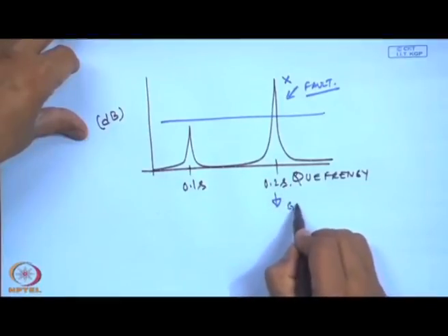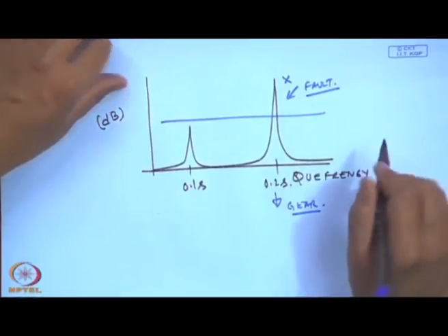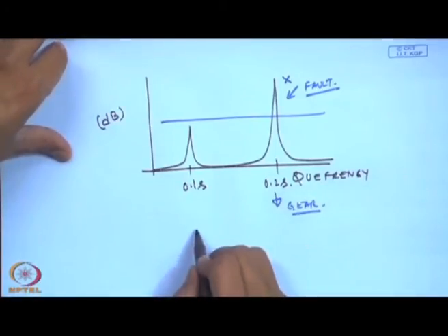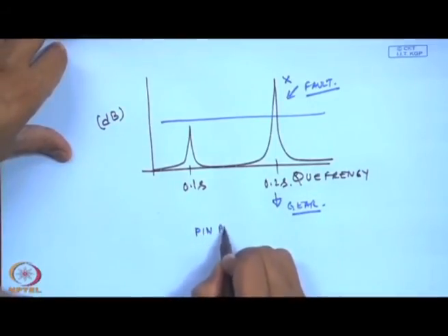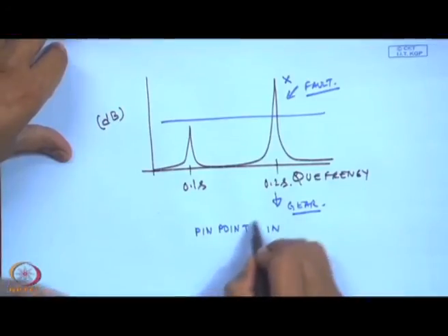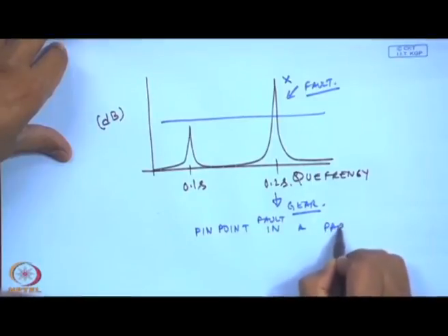In this case, it is my gear. So, we can use such a technique, cepstrum analysis, to pinpoint the fault in a particular component.